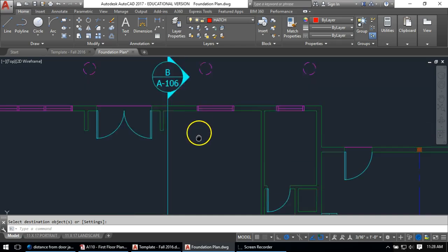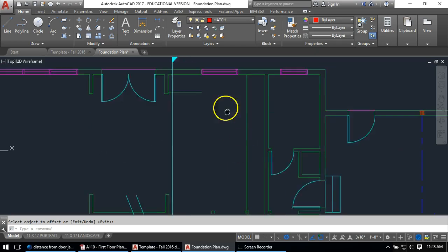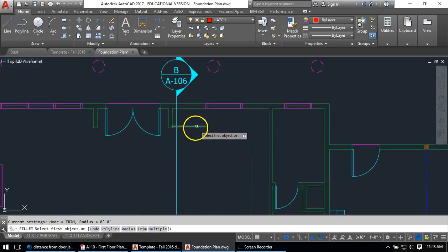Alright, so let me do a kitchen. I'm going to offset 2 feet to draw the kitchen cabinets, because that's what kitchen cabinets are. You can actually see it says 2. There is a dimension on there even. Didn't even need that. That's 2 foot there to there. I can fillet this together.